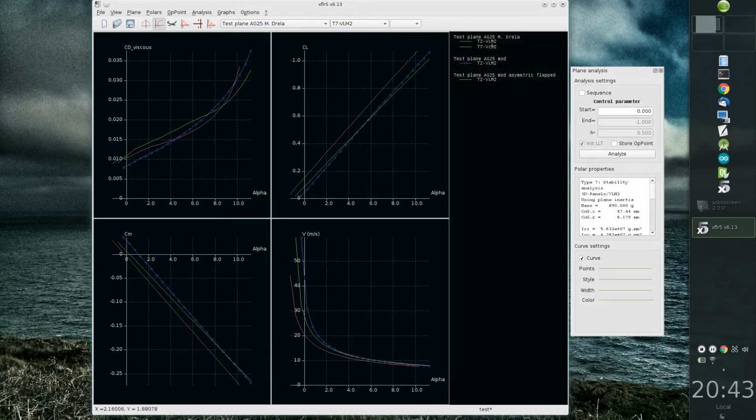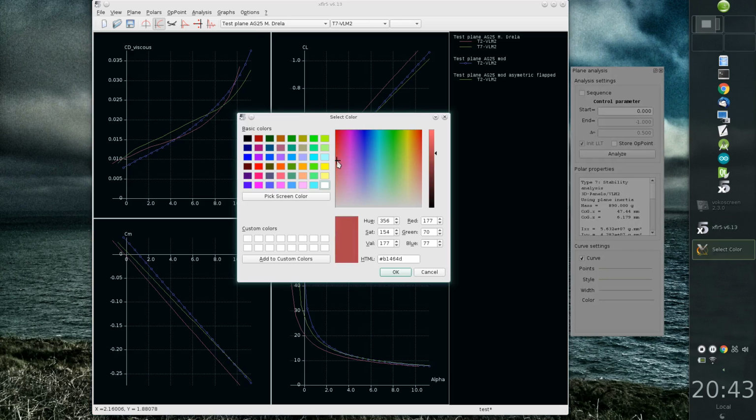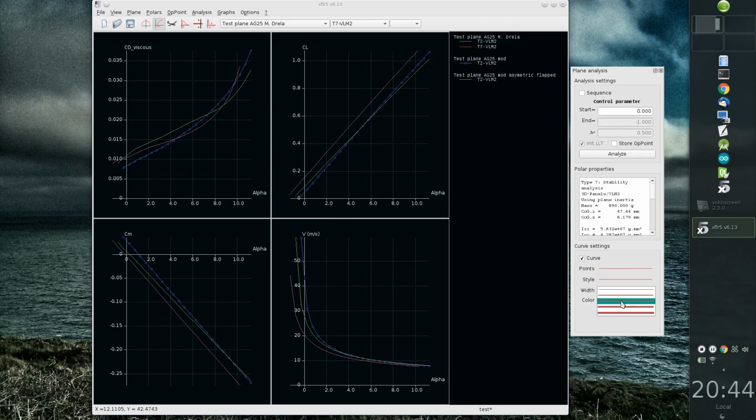So this is the green curve here. We'll use a color similar to the type 2 polar because they're closely related. So let's use this and have a thick line and use a big point here. So we've only got one point, which is where we expect it to be, at the angle of attack minus 0.15 degrees roughly. And it's always located, if the analysis went smoothly, on this red curve. I mean, you should always find them matching, and the point should be located at minus 0.15.